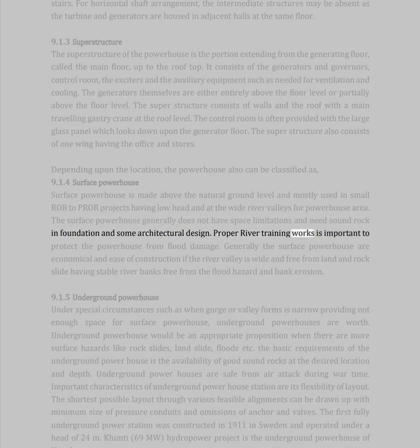Proper river training works is important to protect the powerhouse from flood damage. Generally, the surface powerhouse are economical and ease of construction if the river valley is wide and free from land and rock slide, having stable river banks free from the flood hazard and bank erosion.